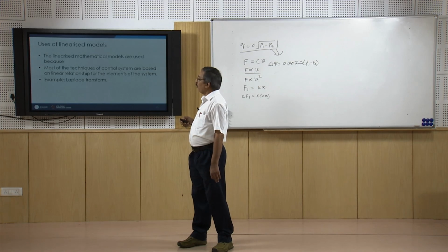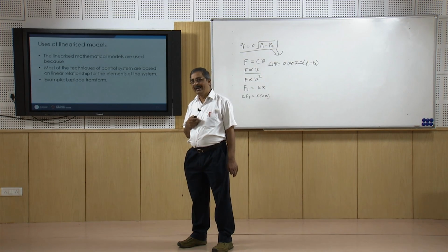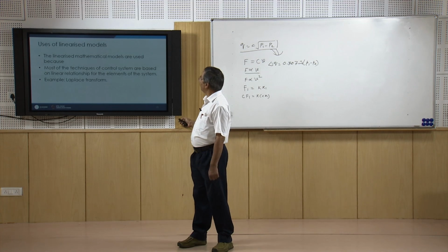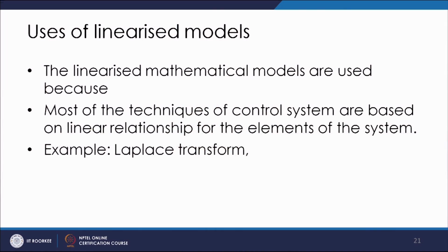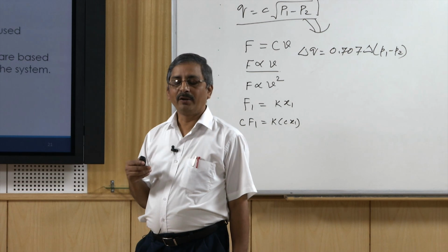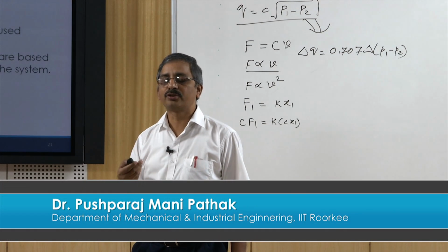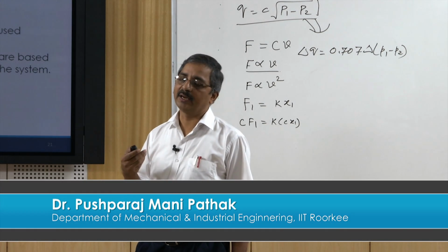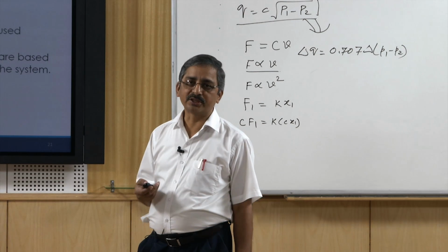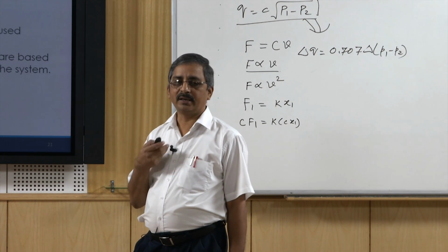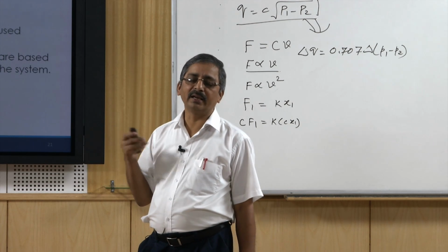Now, why do we want to linearize a nonlinear equation? The reason is that there are ample tools available for linear systems, and once you have linearized your nonlinear equation, you can always use those tools to study the various characteristics of your system, be it stability or its frequency response or any other behavior.